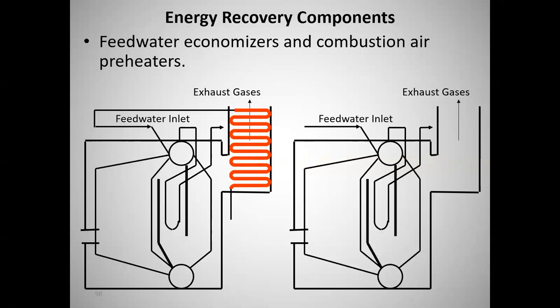When you go into a plant, you can try to look at a logbook and see if that delta T is consistent over time. It's possible for those heat exchangers to get dirty, fouled. They have to be cleaned probably every year, year and a half, 2 years. You need to take that thing apart and clean it out good. If you see that you're running a 20-degree delta T on feed water, and you can look back a couple years into the records and say, wow, we used to run 35, 40, now we're running 20. Something's changed. If the flows and temperatures are comparable, then you probably have a dirty heat exchanger.